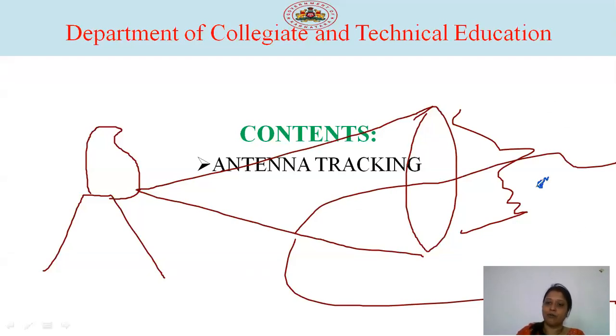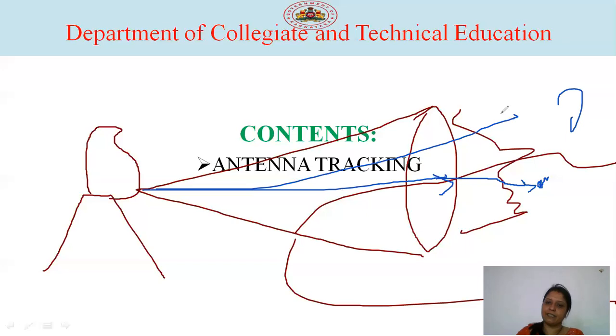Therefore, once the target is searched or located, afterwards instead of the fan shaped beam, they will make use of the pencil type, or very narrow beam width signal. A very narrow, sharp beam is used such that it continuously follows that particular target. Wherever the target moves, continuously our radar signal is following there. Therefore, that process is called the tracking.